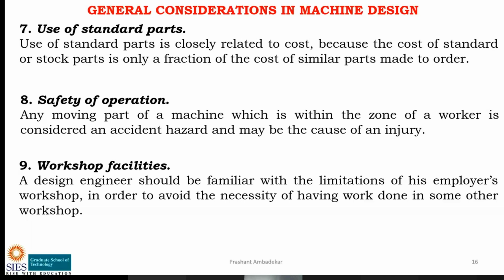So is there any other way, instead of threads, by which the part can be designed so that giving it to some other person's workshop can be avoided? Can it be avoided? This has to be taken into consideration by the designer. For that purpose, he should be familiar with the capability of the workshop in which the part will be manufactured.